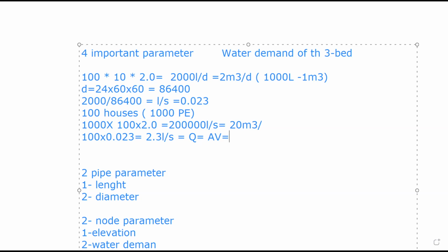If I'm using a square pipe, I will know that this A is length times length. If it's rectangular, length times breadth, whatever. So this is the general way to do the design manually. Once you get your Q, that Q is a function of A times V, and your job is to get your A.